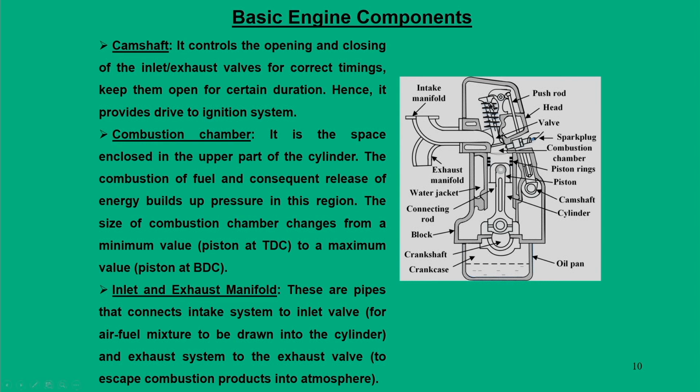The entire thing is governed through a shaft, which we call a camshaft. This camshaft regulates the inlet and exhaust valves for correct timings and keeps them open for certain durations. It also provides a drive for the ignition systems.